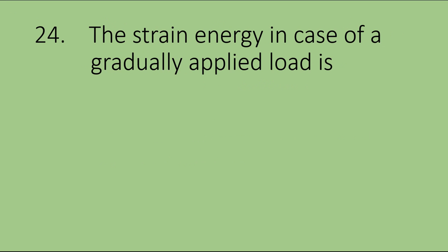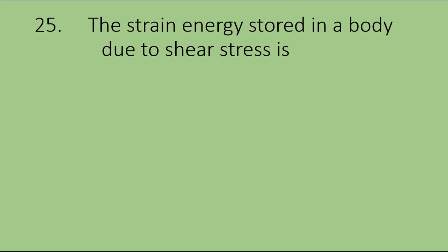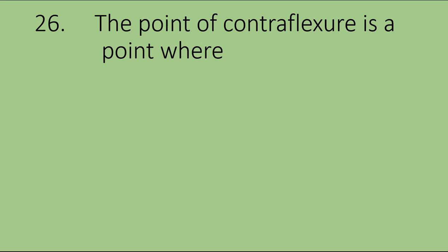24. The strain energy in case of a gradually applied load is. Answer: sigma square into V by 2E. 25. The strain energy stored in a body due to shear stress is. Answer: tau square by 2G into V.